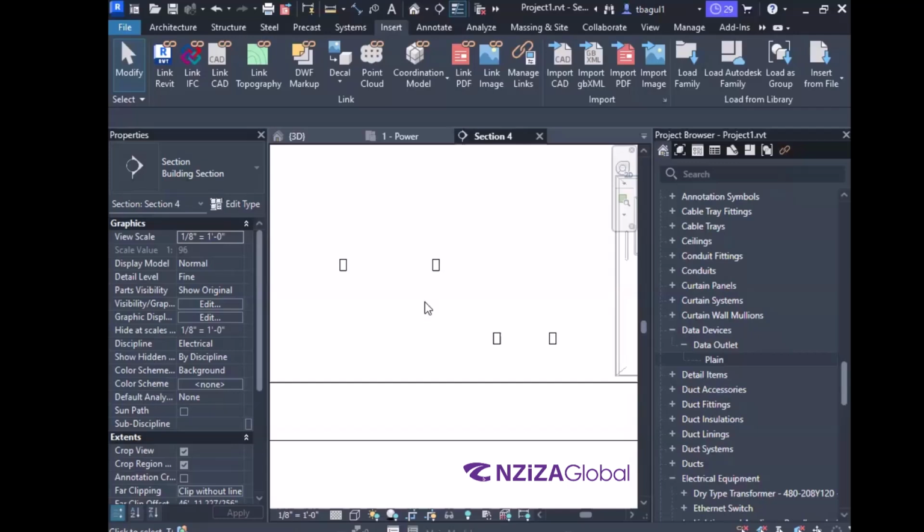One more point. A good point was made over here, that in Rwanda there are standards that maintain the outlets at 2 feet above the finished floor. It is fine. Understood. So whenever you are designing a project, your country's building code laws will take precedence over standards.